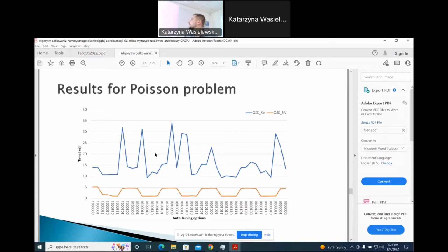We also have QSS in the bottom right corner, and what is this? It indicates the order of loops in our algorithm. Q is the Gauss points, S is the shape function. And it turned out that the QSS version of the numerical integration algorithm achieved the best result for both accelerators.